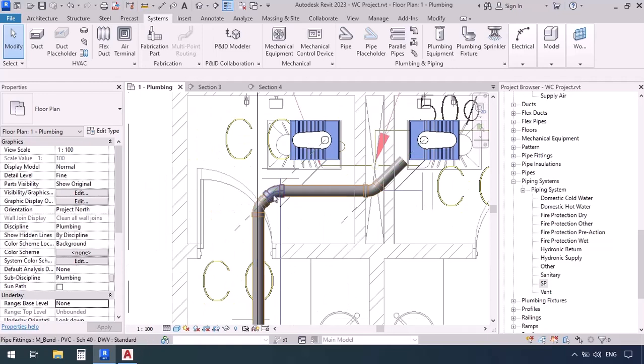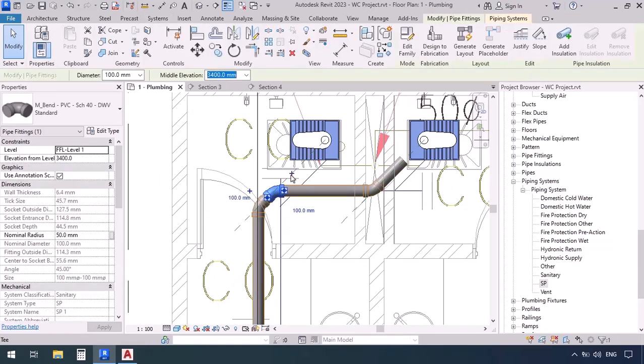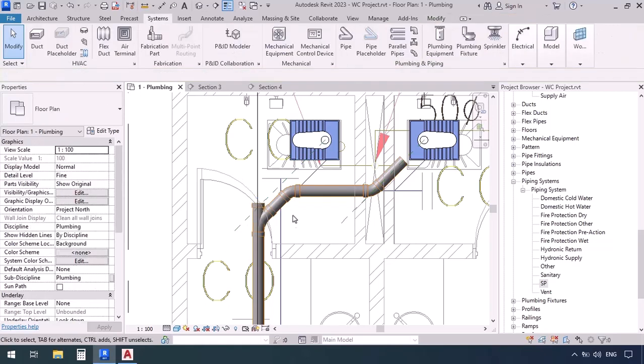Now, right here, I'm going to have to convert this elbow to a T so that we can draw this junction, and then I would have to convert this elbow to a T so I can put a clean out. So it's best that we create a little distance between these two. So I'm going to select the lower elbow and move it lower. And now that I'm moving it lower, you see it just changed from the position we gave to it. So after you create enough distance, convert this one to a T as well as this one.